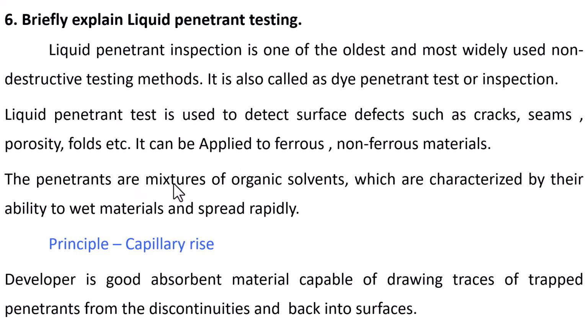The penetrants are mixtures of organic solvent, characterized by their ability to wet materials and spread rapidly. The principle behind the liquid penetrant test is capillary rise. We use a developer. The developer is a good absorbent material capable of drawing traces of trapped penetrant from the discontinuities and back to the surface.